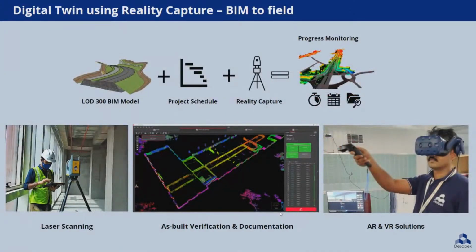Regarding digital twins using reality capture, here we build models by using laser scanning technology. We develop BIM models using reality capture data, and that model can be further used for as-built verification and documentation and also construction progress monitoring.